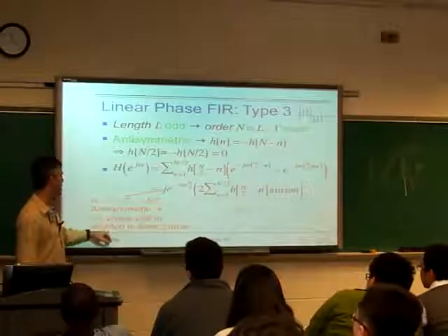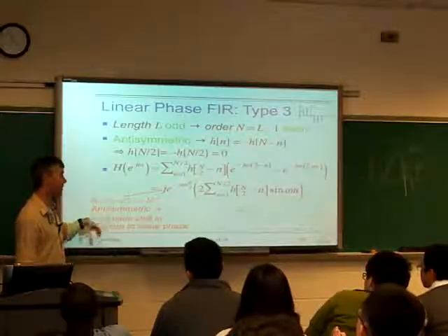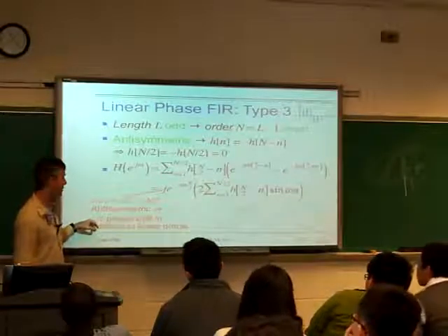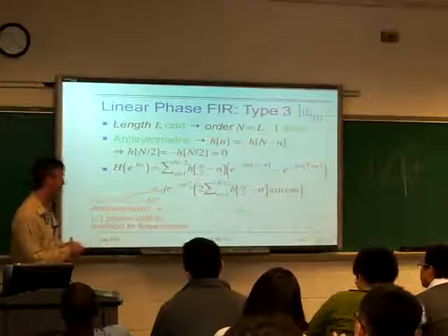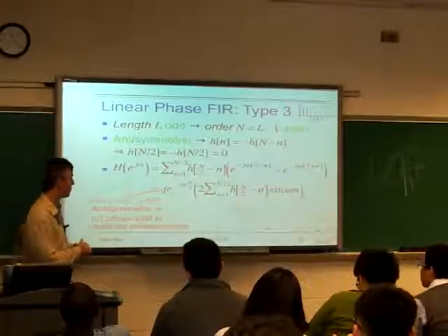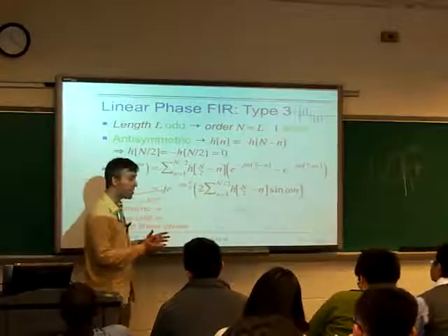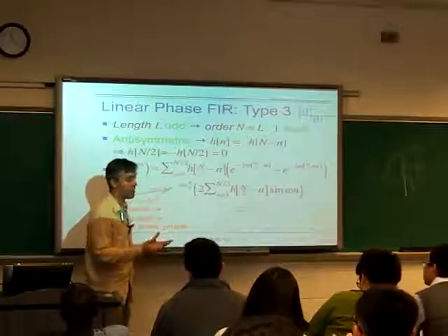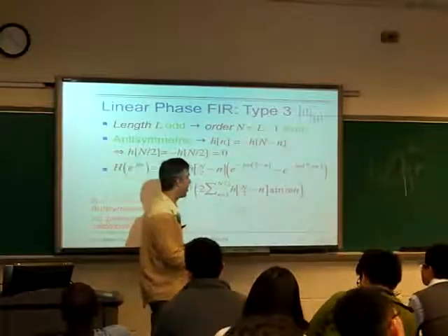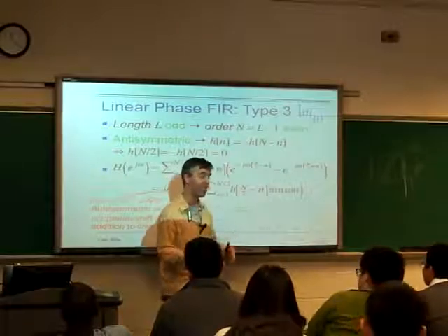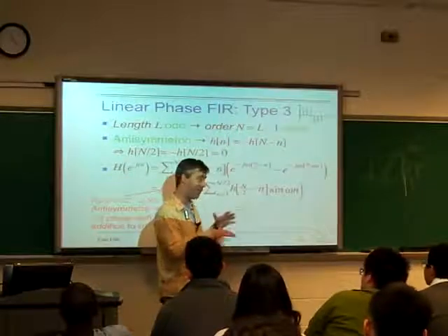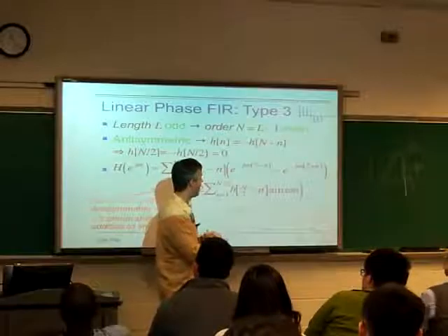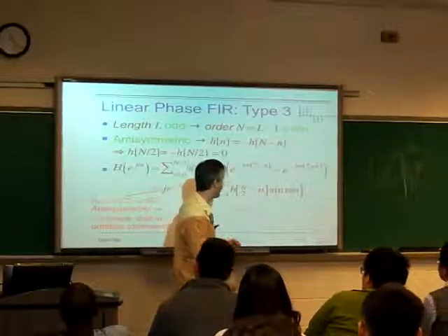So it's basically a pure delay, but it also has this pi on 2 phase shift, basically a quadrature phase shift built in, which is sometimes useful, although most of the time it messes up the shape of your function. But sometimes you actually want a constant quadrature phase shift for all frequencies, and that's how you can achieve it.